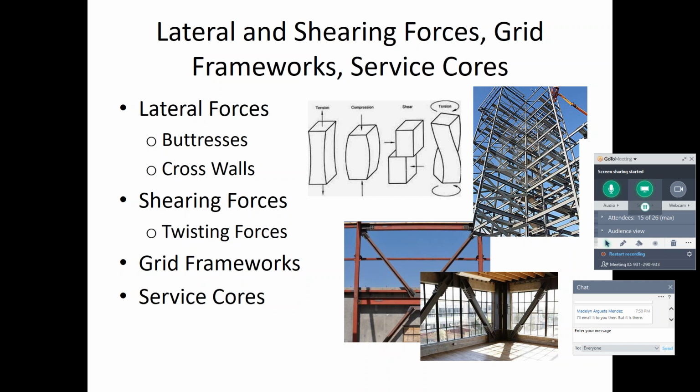All right, so the image that I'm showing at the bottom is our picture of an open grid work. So shearing is where it's moving side to side, and sometimes it's twisting, but it can be resolved by our brace frame, which is this red guy right here. We see it's the inverted triangle within a rectangle, and sometimes it's partially exposed, or it would be back here behind the wall or under the subflooring and then into the ceiling. But these are the same things. You might have seen them in some cityscape buildings.